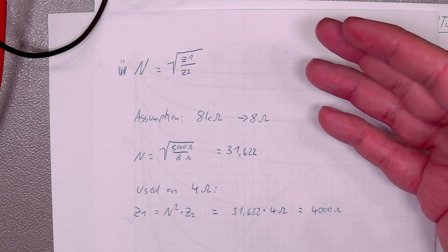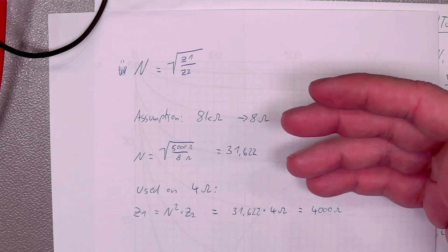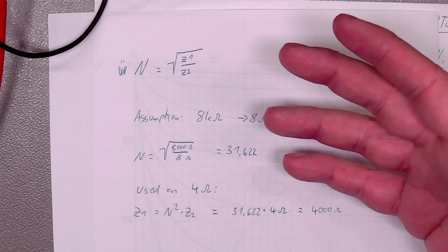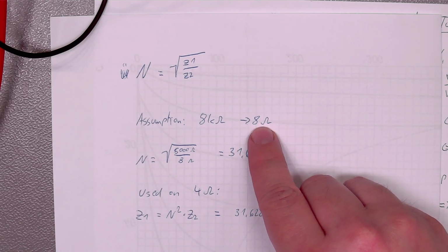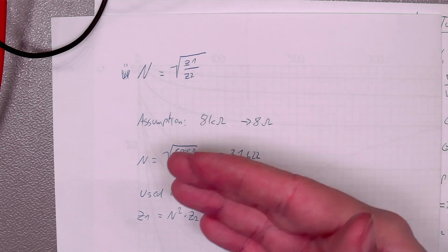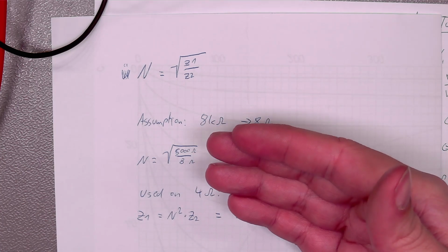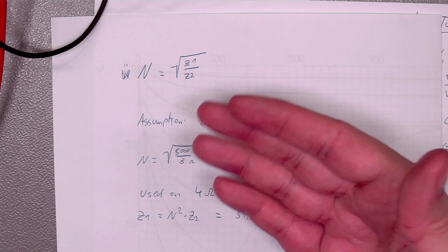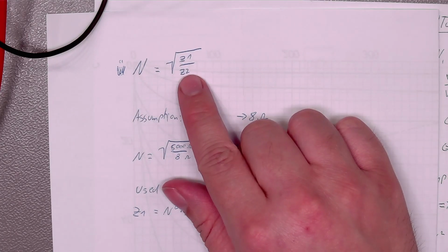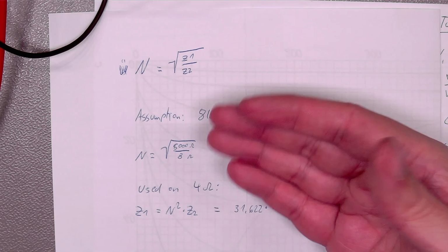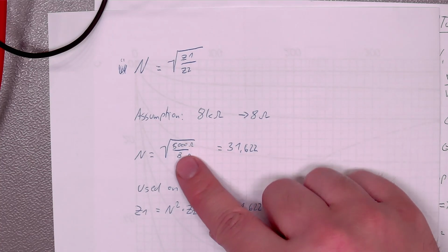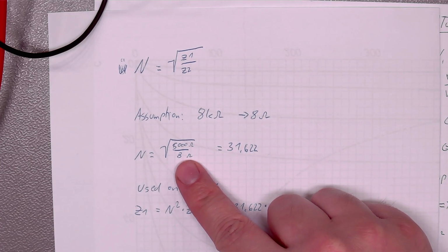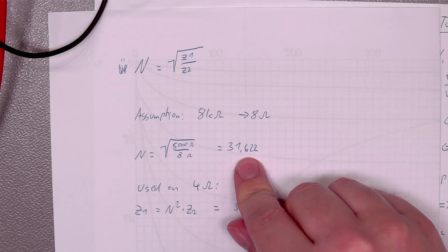Just a quick last-minute addition before we end this video. If you have a known transformer, like you bought an 8 kilo ohm transformer which is used for 8 ohm speakers, but you happen to have 4 ohm speakers and want to know what impedance you can expect and what you have to calculate for, there's also a pretty simple formula. You just calculate the turns ratio again. This time it is the square root of Z1 over Z2, which in terms of this 8,000 ohms to 8 ohms ratio returns a 31.622 turns ratio.